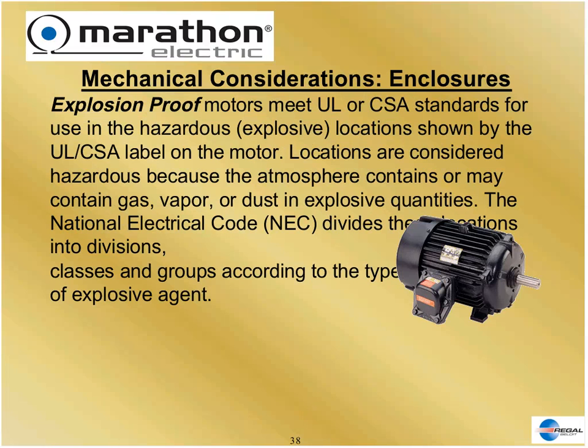Now, sometimes the environment that the motor is in is hazardous or hostile or explosive. In that case, we use a very special enclosed motor called explosion-proof, which is built to very demanding standards mechanically. Parts fit very, very tightly, and these motors are intended to not explode the environment that the motor is located in.